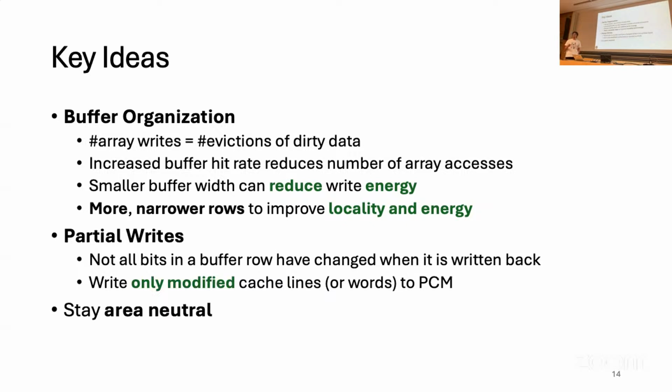And the third key idea is more of a guiding principle throughout the paper. It's not a mechanism like the other two. The authors only consider these organizations if they're area neutral, so they do not take up more area space than a DRAM in comparison. And this is important for memory manufacturers because area directly equals cost.